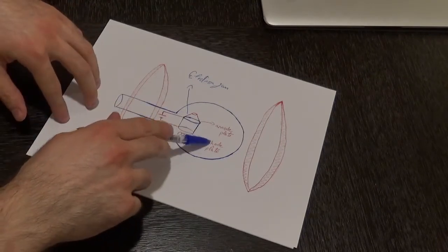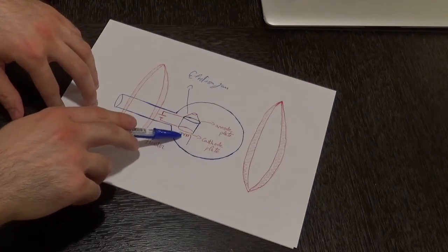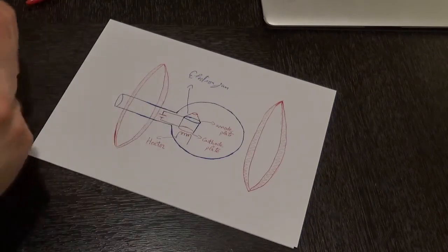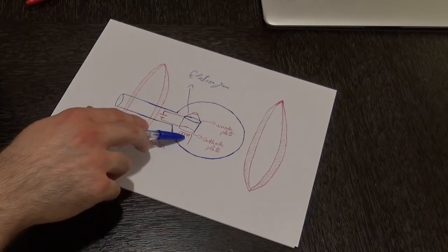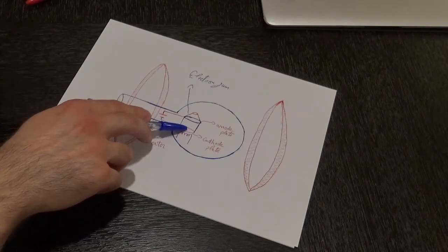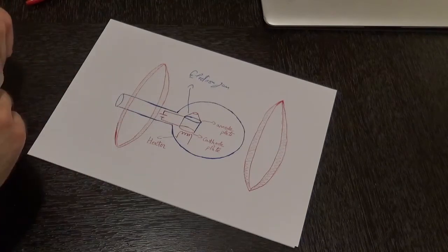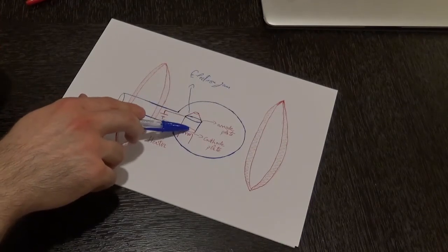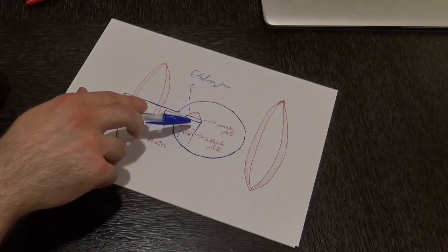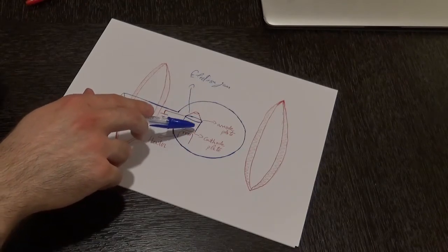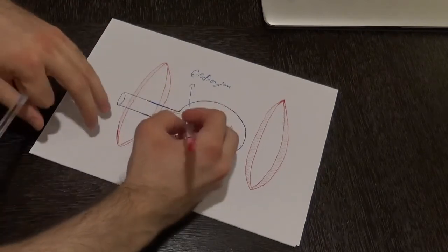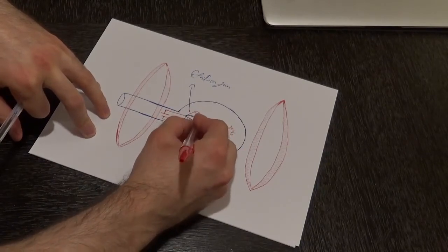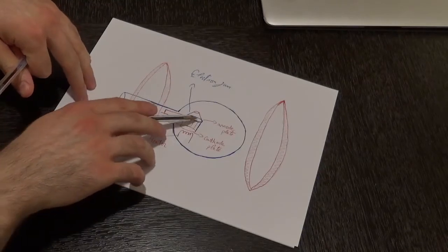In addition, that cathode plate is actually equipped with a heater. So right beneath that cathode plate we have a heater in order to render it hot enough. Therefore, the cathode plate would be able to generate a stream of electrons. And the presence of that power source is going to be needed in order to supply the electrons generated by the cathode plate with an accelerating voltage so that they can be transmitted from the cathode toward the anode. So over here we have a stream of electrons being generated by that cathode plate and directed by that accelerating voltage toward the anode plate.